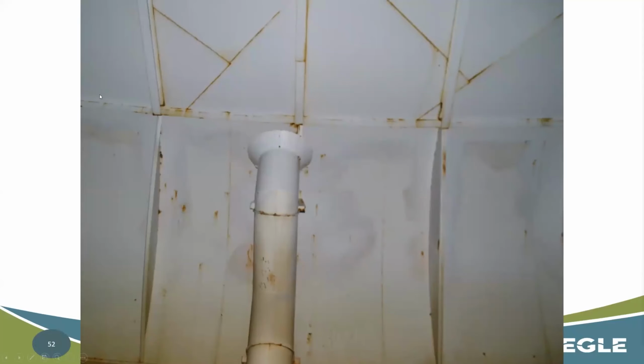This is another example of an overflow, but this is probably a more ideal situation. So you have this 36-inch diameter overflow here. Notice that it's completely rounded, so you can have water pouring in from any side. If you have a little bit of ice chunk coming up to this point, it's not going to prevent it from still getting water from this side.